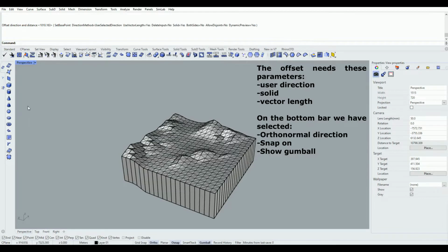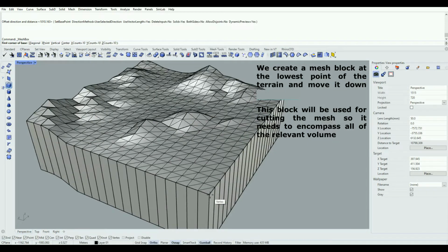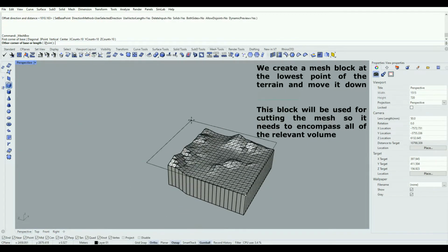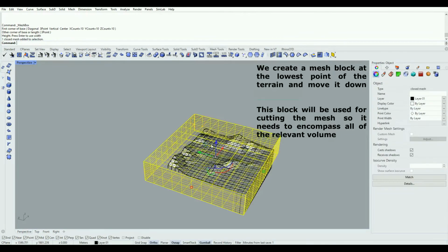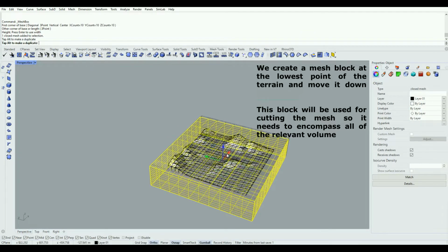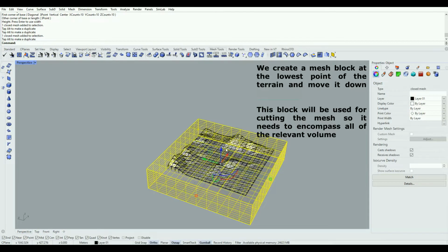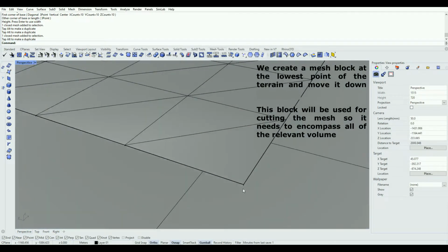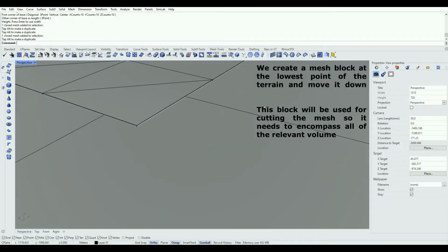With the extrusion complete, we create a box to cover the lower part of the extrusion. This lower part will be removed in subsequent steps. To ensure that the cutting operation, Boolean Difference, runs without any problems, we offset the box by 1 meter. Otherwise, we may inadvertently create holes in the lower parts of the object.